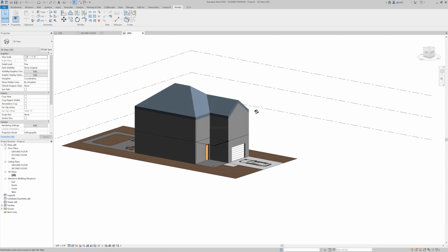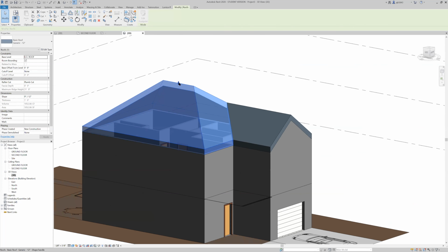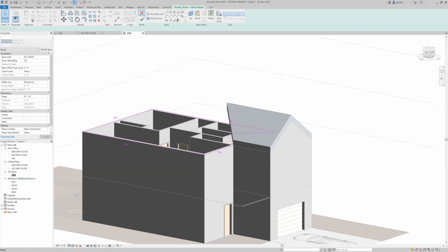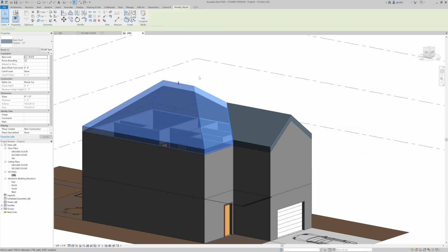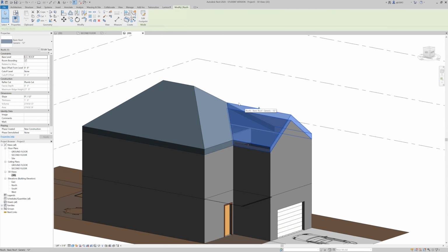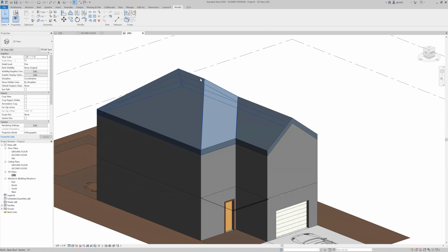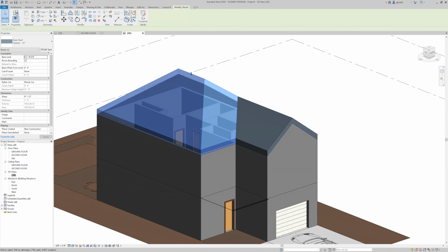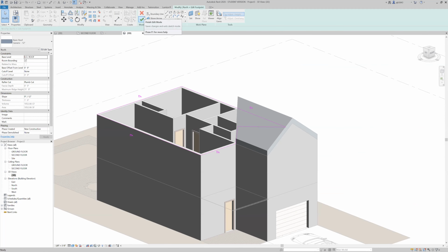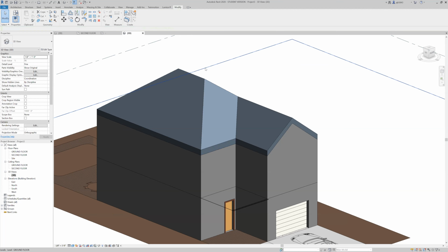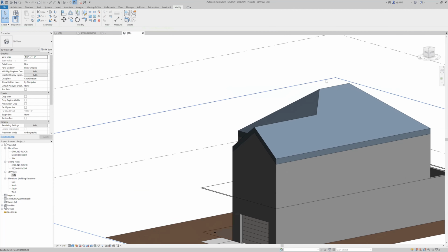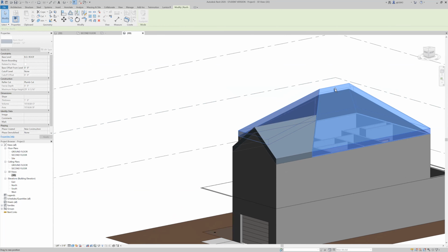The only thing I want to adjust here aesthetically is just bring the top of this down a slight bit. So if I go ahead and select the roof, I want to just modify a sub element, if I am able to. Any idea why that's not coming up, Emily? No. I mean, I believe the first time you just changed it by adjusting the slope from 9 over 12 to something else. Yeah, we can do it right here as well.